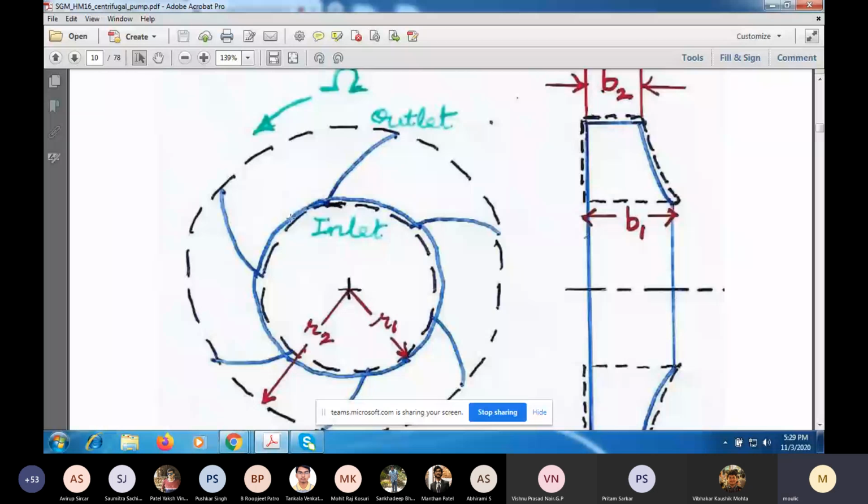So there will be slip at the surface. The surface will rotate, it will not drag the fluid in. And at the inlet, the fluid is axial, it has no swirl. So the fluid will not acquire any swirl until it enters this space. Once the fluid enters here, the impeller blade, by pushing on the fluid and producing a relative velocity component normal to this surface, will generate swirl.